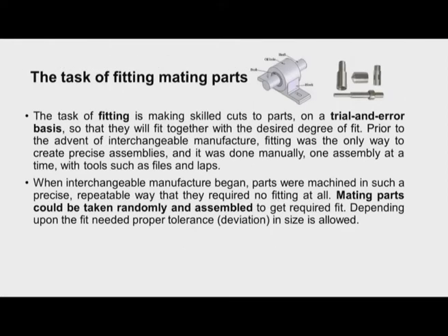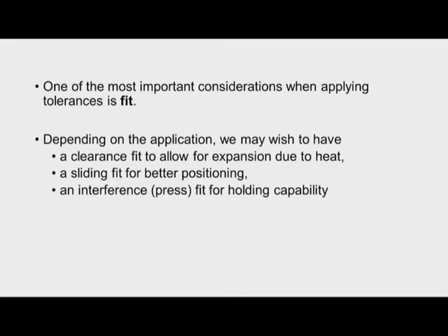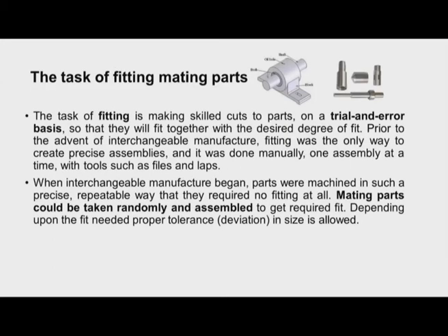Now let us try to understand what is the meaning of fit and what is the task of fitting the mating parts. Here we have a bore hole, a part wherein there is a hole, then a bush, and then a shaft. We have to assemble all these three parts. The bush will be in contact with the body of this particular bearing, and there should not be any rotation or movement between bush and the body.